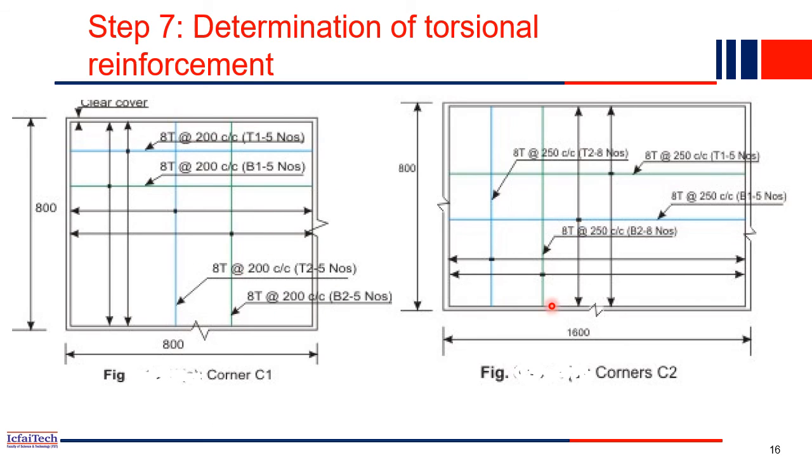So that's how we completed a complete two-way slab design from basic scratch. Ultimately this design we have to give to the site engineer. Now he will make the exact reinforcement pattern at the site and he will cast the slab. So that's how we completed our slab designs. One way slab design and two-way slab design we have both discussed in this class. Basically you have to provide the reinforcements as per the design, and our slab should be sufficient.